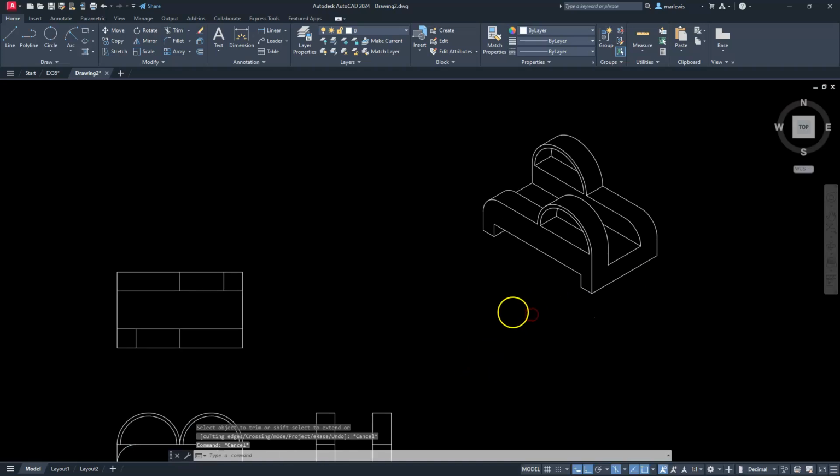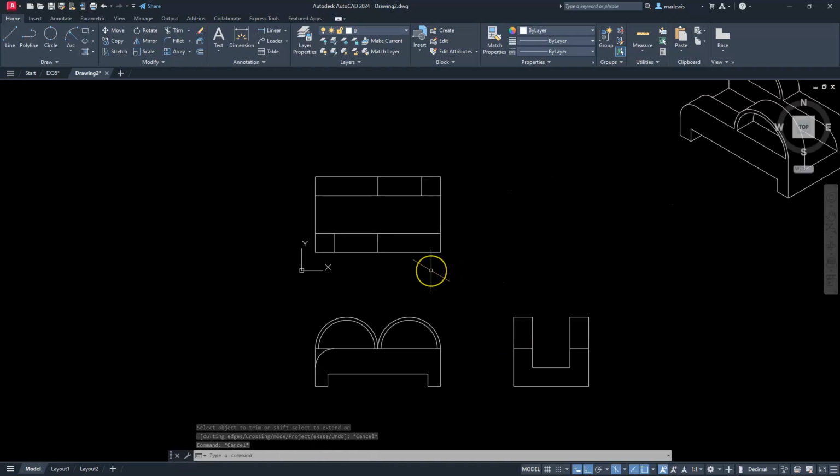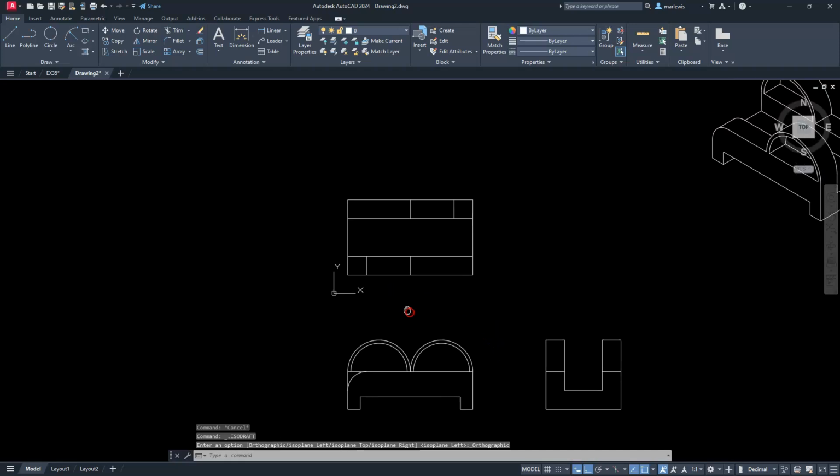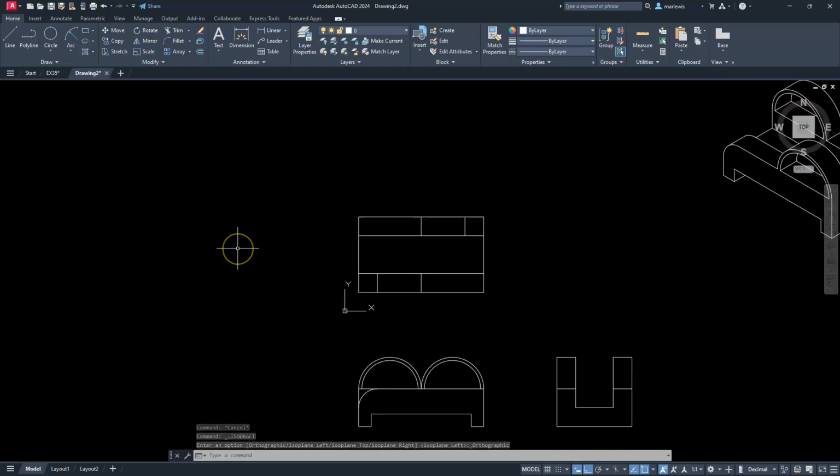Alright, so going back over here to the drafting portion, the first thing I need to do is figure out what size title block I'm going to use. Let's go ahead and turn the ISO draft off, and then I'll create a rectangle. So A size, B size, really doesn't matter, or even a C size. The concepts will all work the same. Depending on what title block size you use, it's going to determine what scale factor you're going to use, whether that scale factor is a lot larger than what it needs to be or smaller. That's all determined on the paper size.